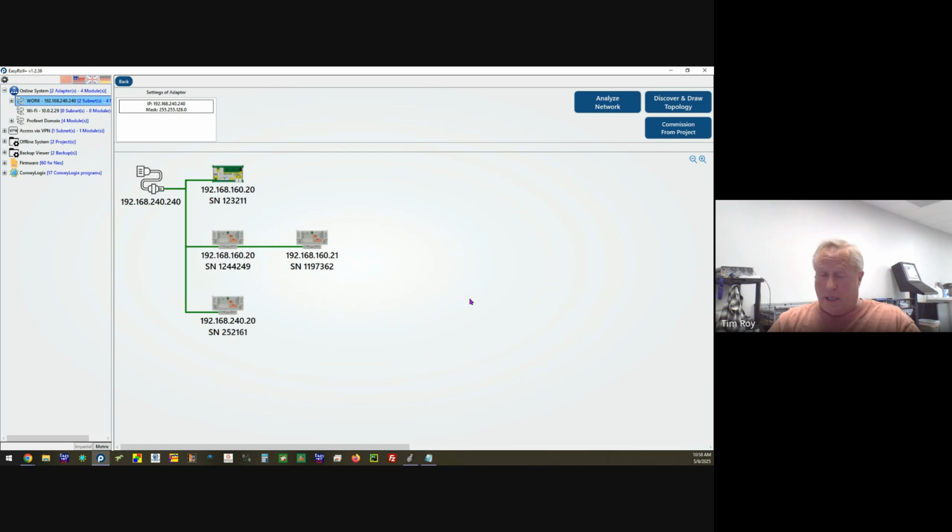Then it says, okay, initiate auto configure. Look at my left port. Do I have a connection? No. Look at my right port. Do I have a connection? Yes. That tells us two things. Number one, yes, I can be node 1. And number 2, my direction of flow is left to right, simply by not having an Ethernet cable on the left port. I'm node 1, and my flow is left to right.